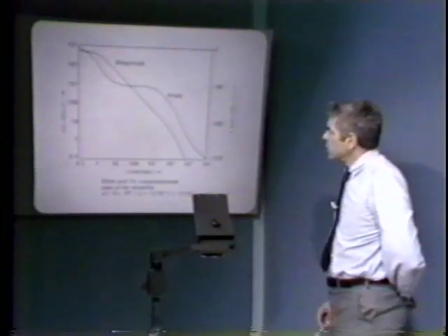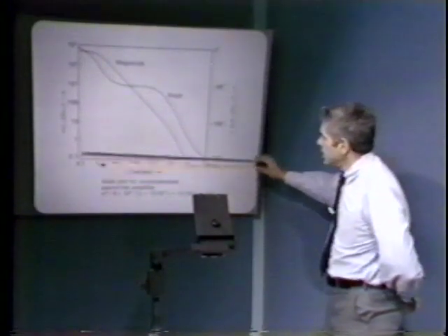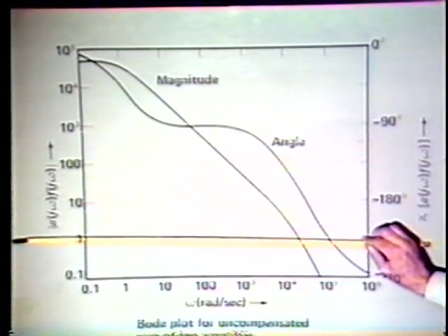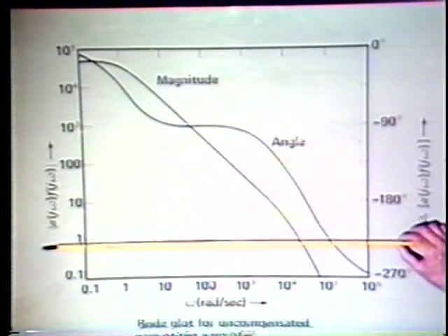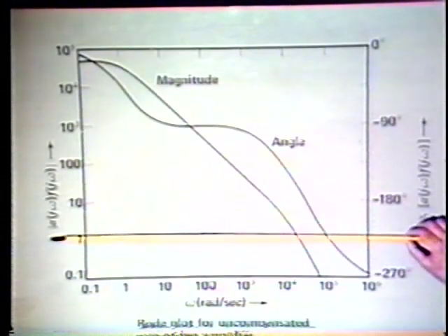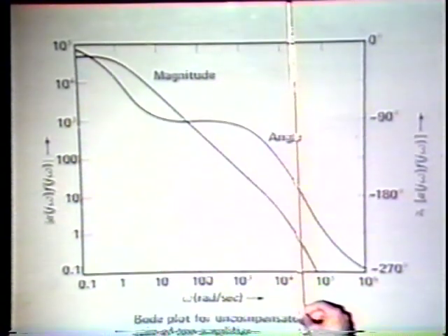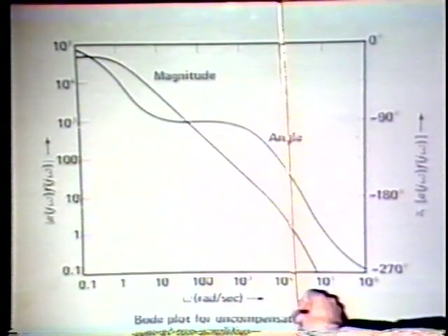And if we look at the phase margin of this configuration, recall that what we do is look at the unity gain frequency, the crossover frequency, the unity gain frequency associated with the AF product, which is right here, and that frequency, if we do it with some accuracy, works out to be 2.4 times 10 to the 4th radians per second. So this is about the unity gain frequency on our plot.